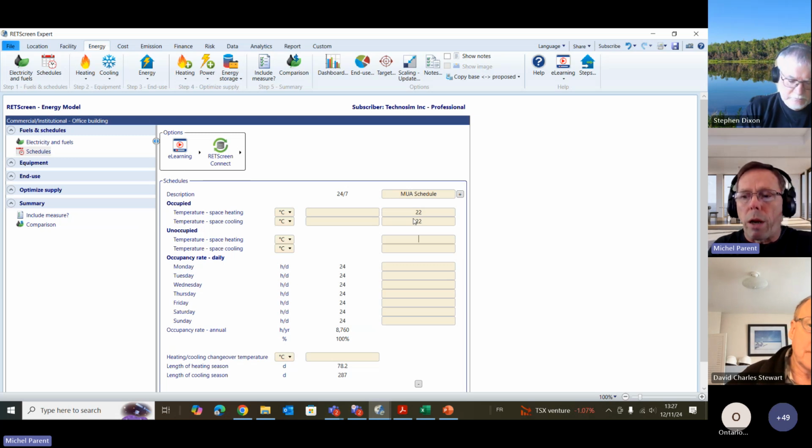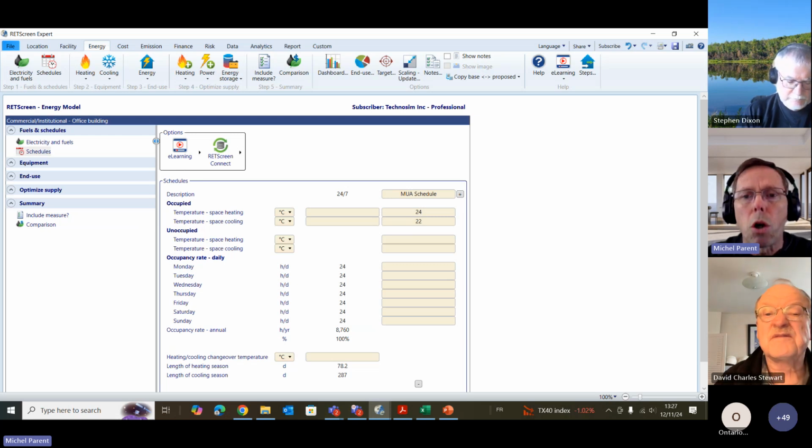This is the set point at which the heating degree days for that makeup air unit would be defined. And it's typically, and I said last week, that last session, I said, don't really ask why. I mean, we could go into the details, but you have to enter it as it stands now, 2 degrees above your space temperature set point for a normal makeup air unit, unless your makeup air unit supplies at really cold temperature.